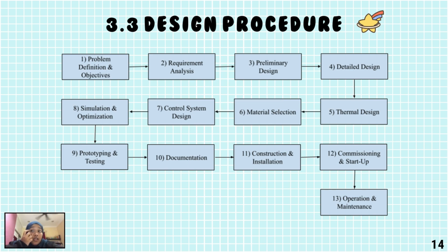Engineers should calculate the mass and energy balance and choose the type of column based on factors like separation complexity and cost. This provides a framework for the detailed design, and the detailed design involves calculating the number of stages needed for effective separation using methods like the McCabe-Thiele method. Engineers then design the column's internal components such as trays or packing material and determine the appropriate column height and diameter to handle the required capacity.